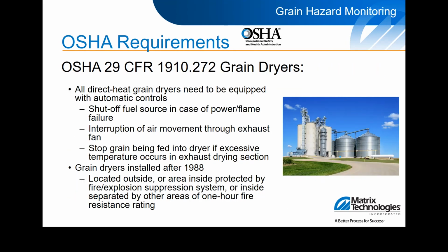Grain dryers are a crucial part of most grain handling facilities. This allows the flexibility to store both wet and dry products at a given facility. In addition to the requirements of OSHA, NFPA 86 also provides some guidance for standards on ovens and furnaces to help identify instrumentation controls required for the burner management systems. These requirements typically drive most grain dryer manufacturers to supply a separate control system used by the grain dryer, but care needs to be taken when implementing or migrating these systems into a plant-wide control scheme to make sure all requirements are held. Some grain dryers will also have multiple gas trains or heating elements for different zones, which each need to follow the same guiding principles.